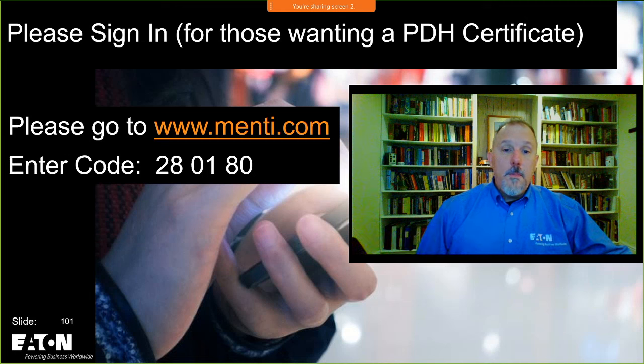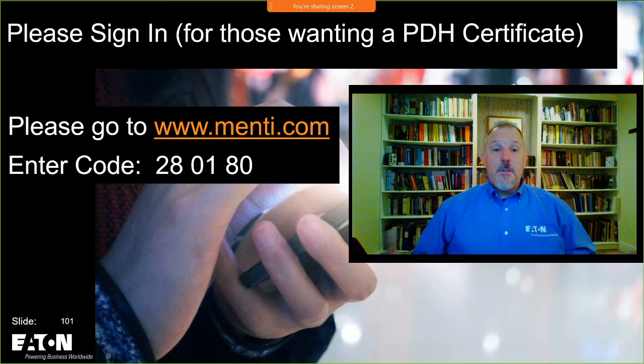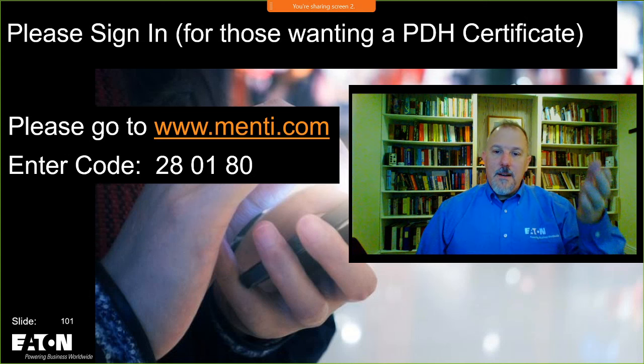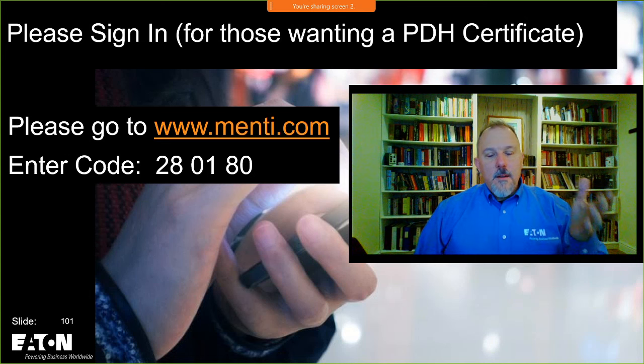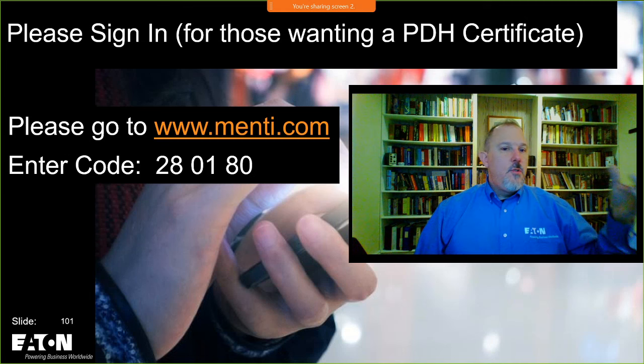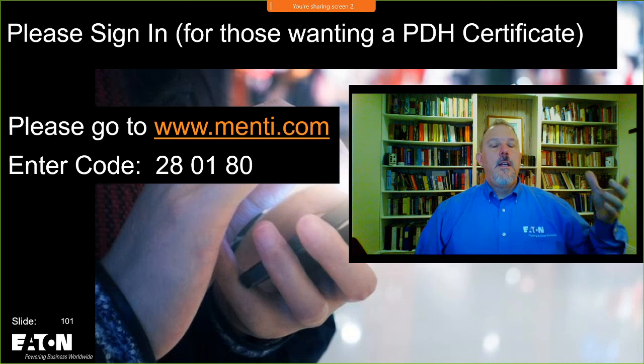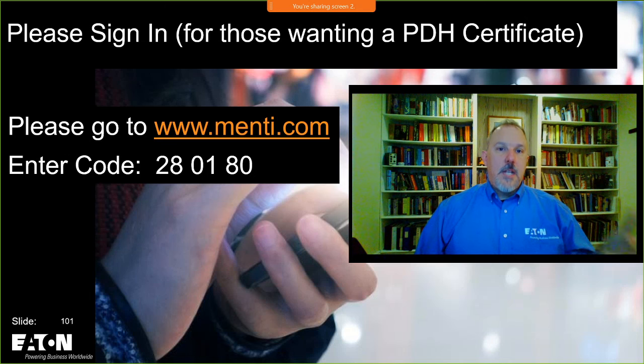If I have an old appliance, and my dryers and my washing machine came with me from my other house, they were built to a standard where they didn't have GFCI protection built in, even if the new standards required it. That presents a hazard in new homes. So the requirement in 210.8, now I'm going to get on my soapbox, is there so that if I bring old appliances, or anything that is an older product that doesn't have GFCI protection, it's going to be afforded protection.